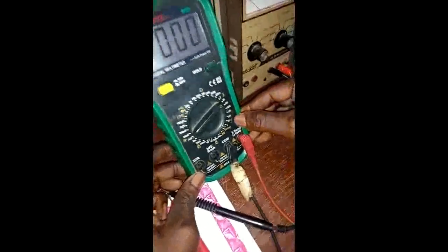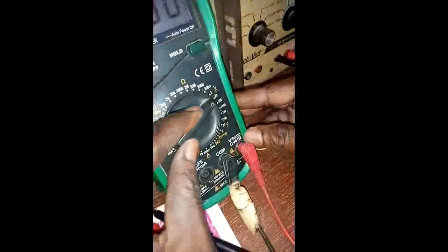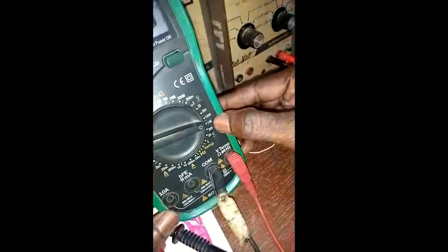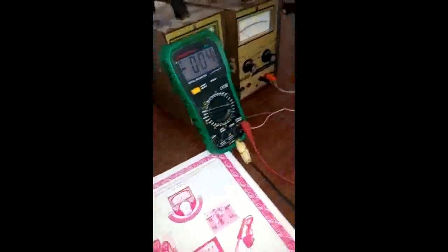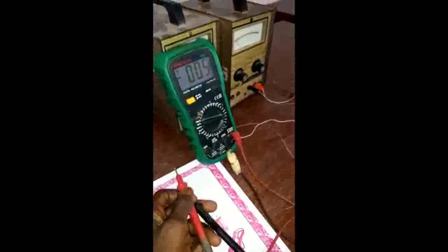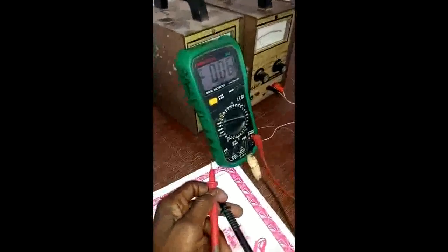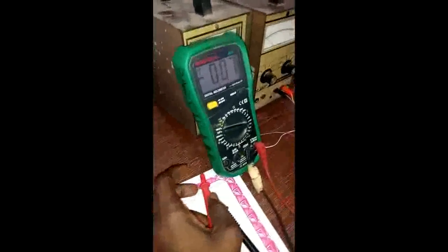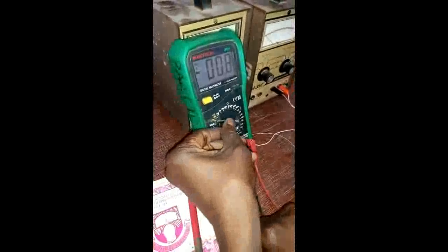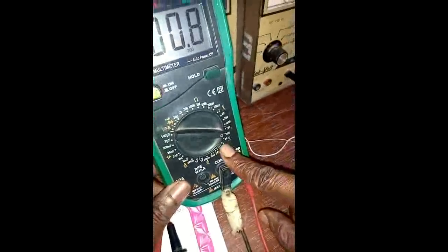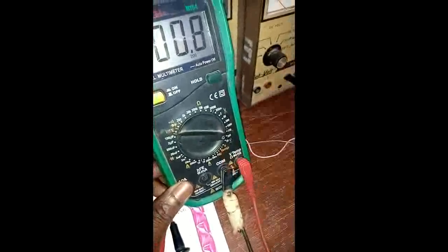So for that of the AC voltage as well, you can come down, you can see it. The maximum this one can go is 750 volts, which means you can even use this one to measure what is coming out from the power supply. The one you are using, that is the AC voltage that we have connected our power supply onto. Then the next one is 200 volts, 20 volts, up to the minimum of 2 volt range. So that is that.